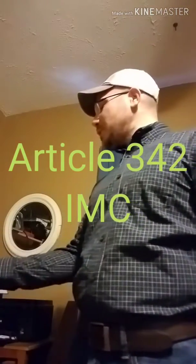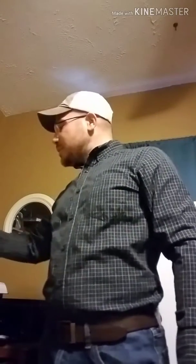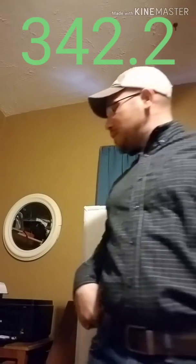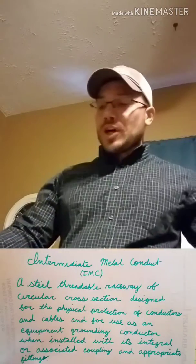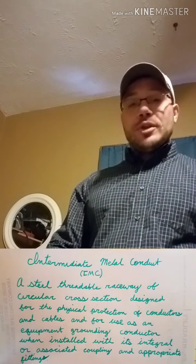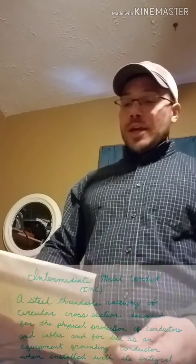All right, go ahead and turn to Article 342, Intermediate Metal Conduit, type IMC. Article 342.2 is a definition. The definition of intermediate metal conduit is a steel threadable raceway of circular cross section designed for the physical protection of conductors and cables and for use as an equipment grounding conductor when installed with its integral or associated couplings and appropriate fittings.